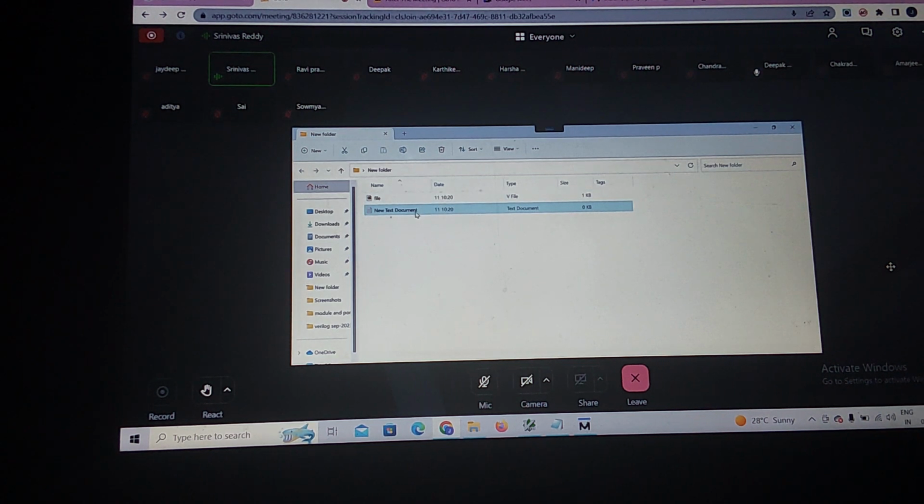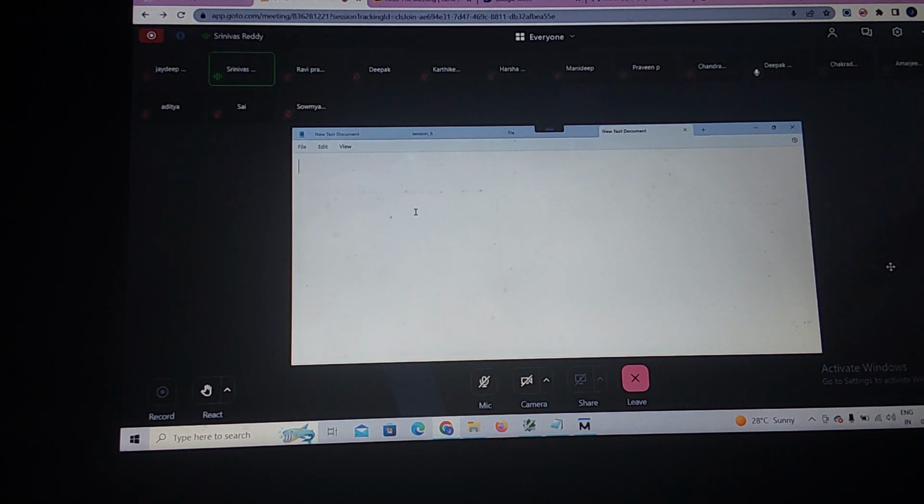Now I need to write the run.do file. So what do I need to write in the run.do file? Will it work? Right? Verilog file.v file name, then vsim the testbench module name tb. Then if I need a wave, I'm going to add the wave. If I don't need a wave, then I can use the run command. Correct.